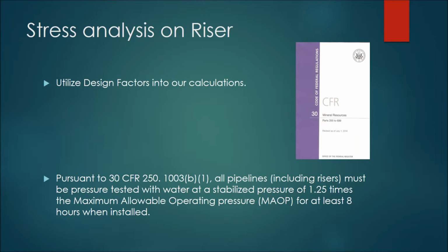High pressure water is pumped into the riser, which must be stabilized at 1.25 times the maximum allowable operating pressure, or MAOP. For our project to have any credibility, we must simulate this hydro test in our calculations because of current government regulations.